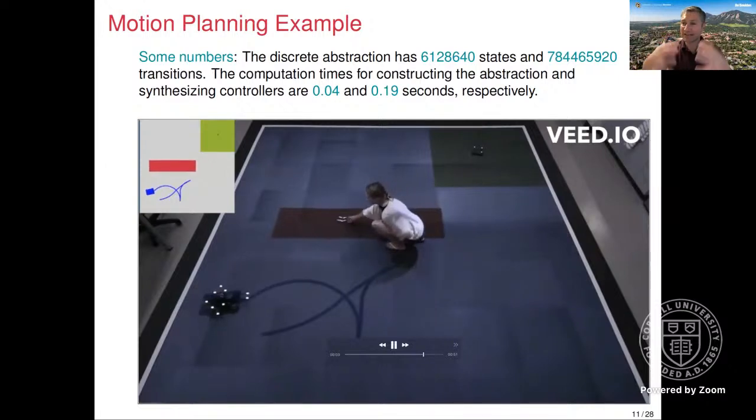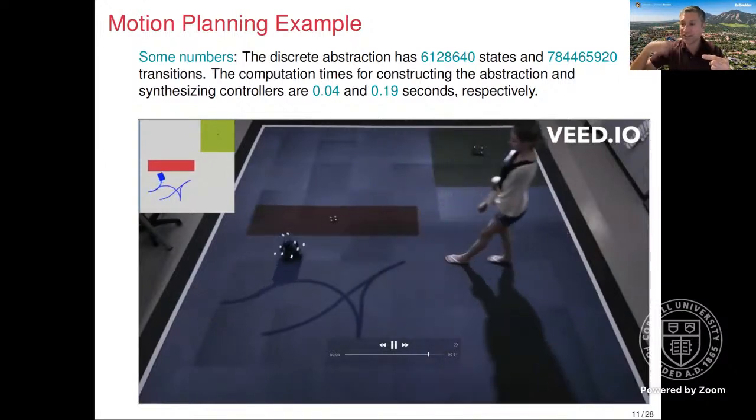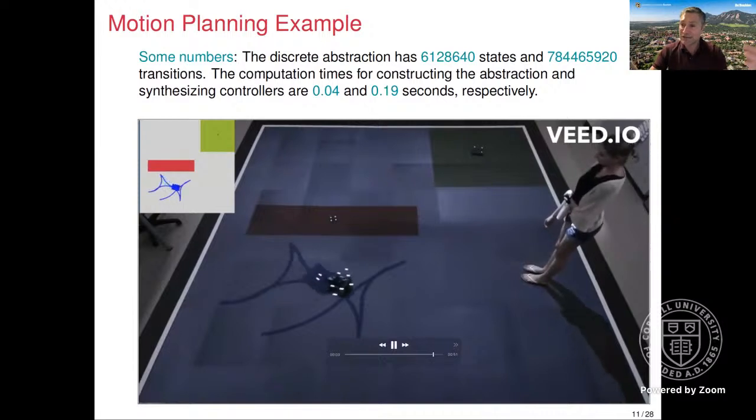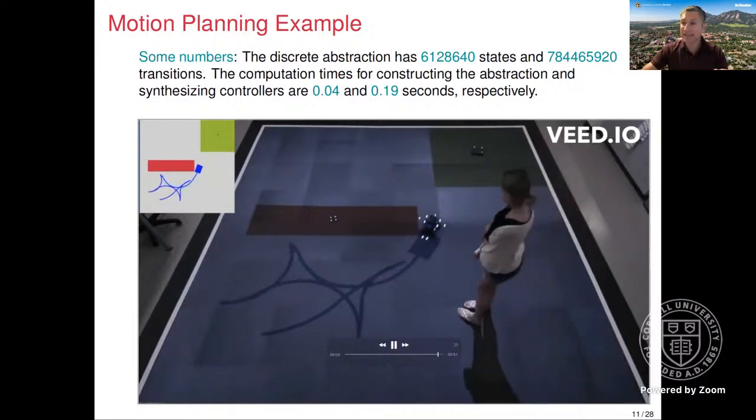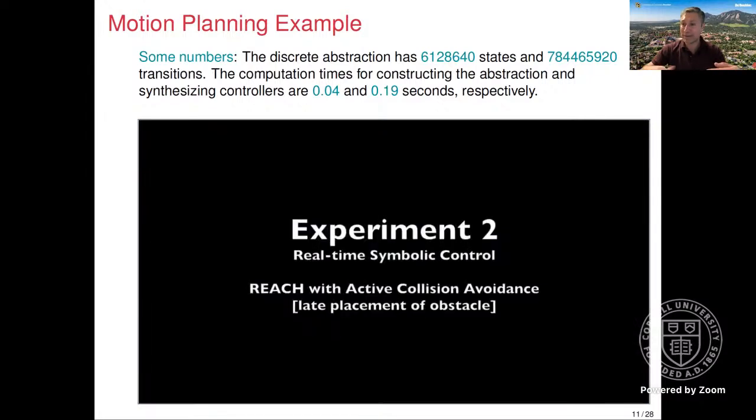So if something is algorithmic, the computer, if it's fast, can actually regenerate the controller on the fly based on the new environment that the car is facing, and is able to come up with a new plan. And based on that, is able to navigate. And of course, depending on how fast the pedestrian jumps, how fast your car is going, it might be the case that when I apply my systematic controller synthesis, it says the domain of the controller is empty. That means I cannot find a controller given this situation, right? So all hope lost? No.